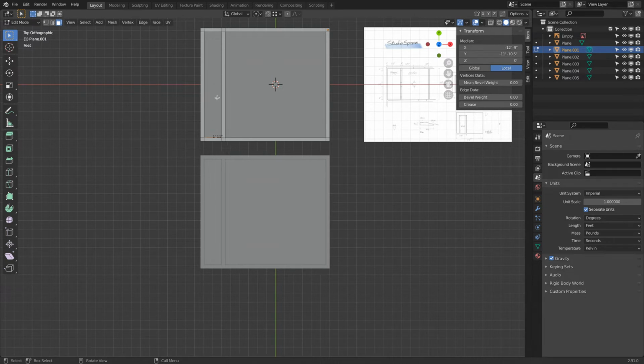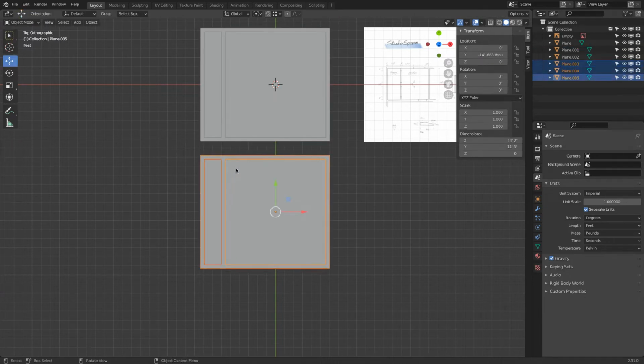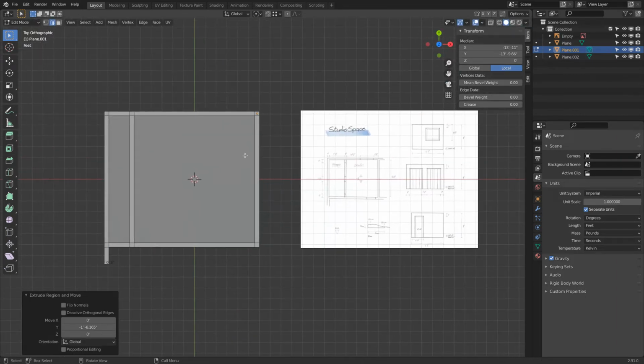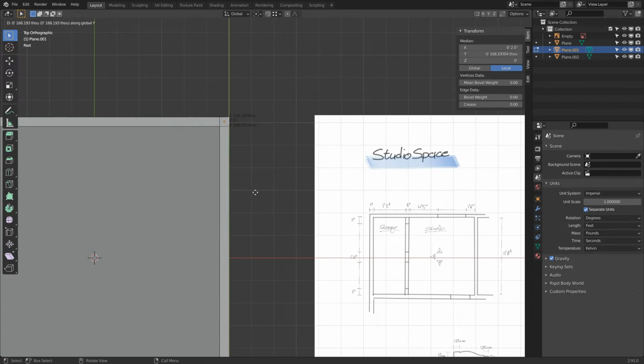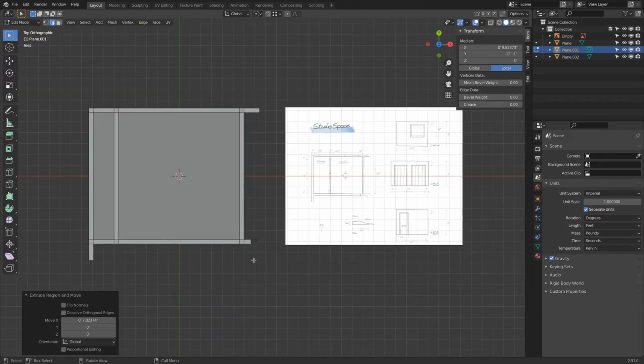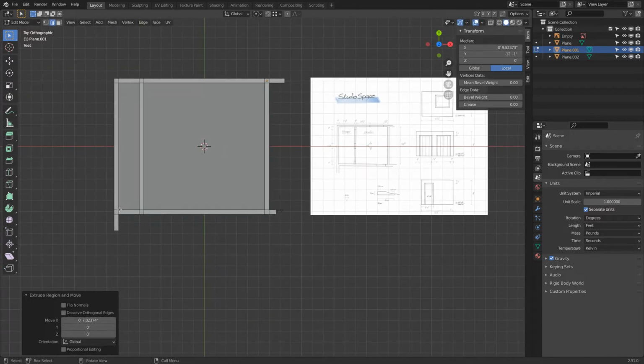Why do I actually like process one more? So the second version here I will delete is for a very simple reason. So let's say for presentation purpose, I want to add little wall fragments. So here I have exactly the wall thickness I could drag out. Previously I only had mitered edges. I didn't have actually wall thickness lines. So that's the reason why I like this one more. Also, adding all the details for doors and windows openings. It's actually a lot easier in this view too.